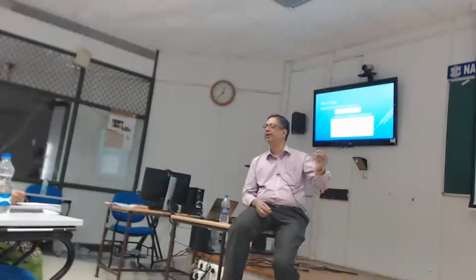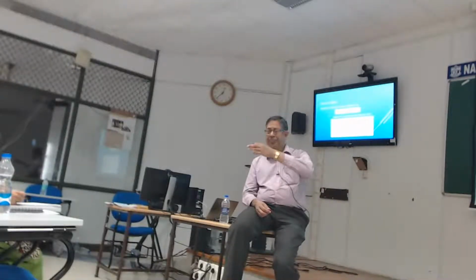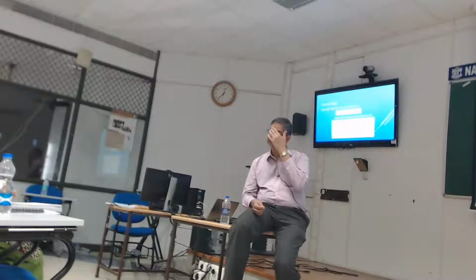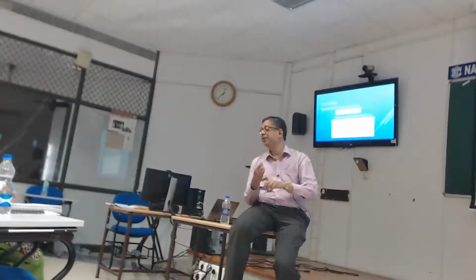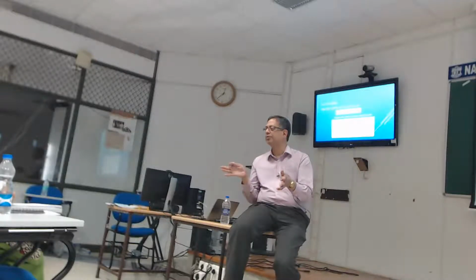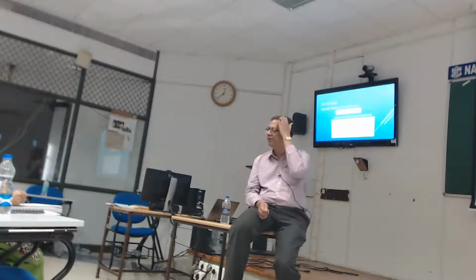Can we relate the interaction of kinematic and inertial forces to the time period of soil and structure? The natural frequency of the soil is very easy to work out. It's Vs over 4H. But often that's not the highest response the soil does, because it softens and changes as the earthquake progresses. On top of that, you've got the time period of the soil changing all the time, part of the fun, and you've got the building which does not change its period at all. You're trying to put all of that together in one parameter. That's not possible.